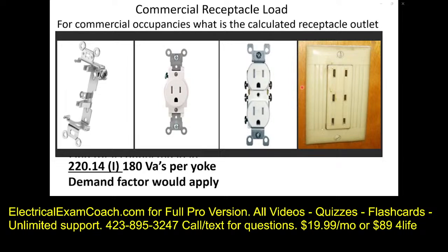There are demand factors that are allowed to apply to a whole load calculation like this. Our question was just asking for how much per yoke, so we're not going to apply anything, but we're going to learn in the next question how to apply the demand factor to this portion of the calculation. And we select B.